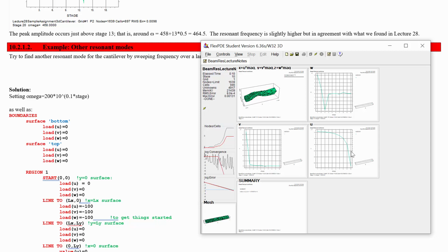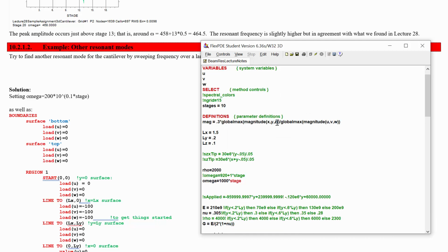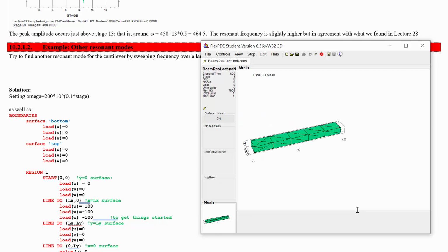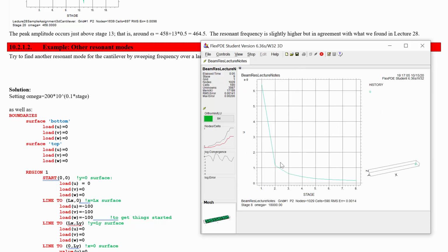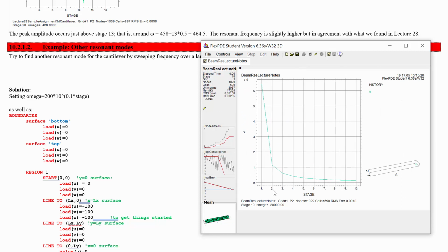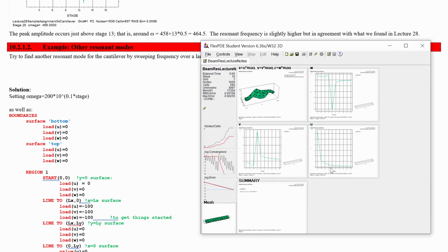This looks like we might be zeroing in on some kind of a longitudinal thing, but it might be the complementary longitudinal stuff that's happening from the twisting there that's going on. So maybe above 10,000, let's say 10E3 plus this. Oh. It looks like we just missed one maybe. But that might have just been that torsional mode there.